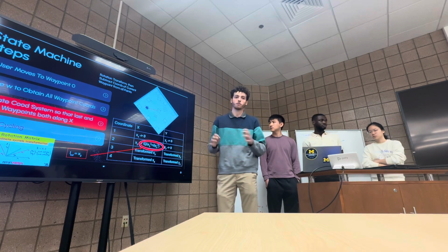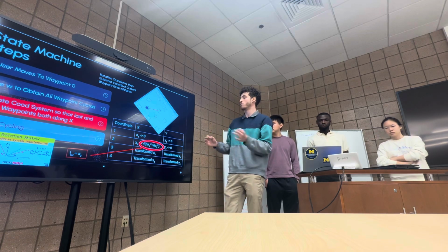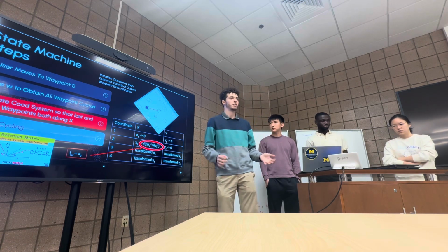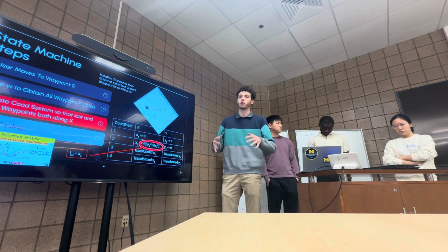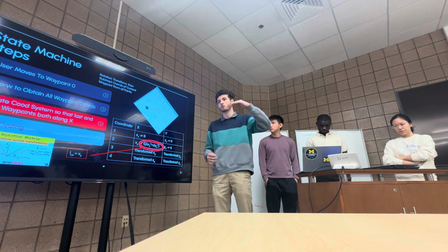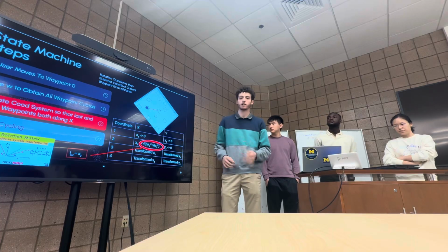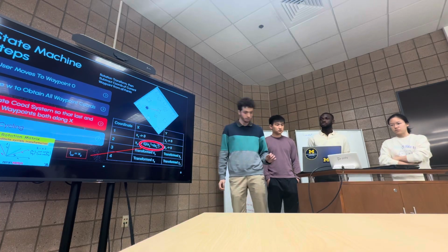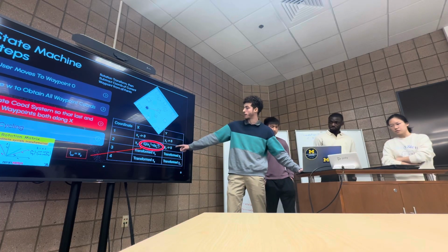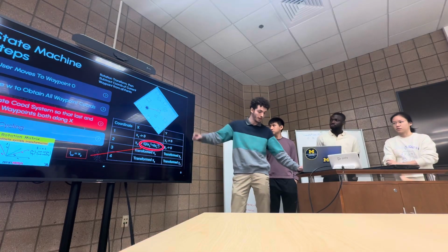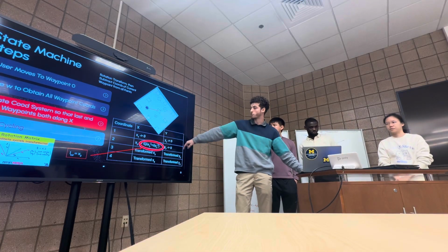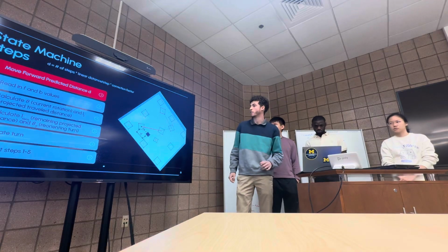We only want to save the rotation, because with rotation matrices, you can multiply them by each other to save the full transform, which will allow us, whenever a new waypoint is added, to just feed it through that set of transforms to get its new coordinate in the rotated system. This will also create the effect that our y coordinate is now just our offset along the F and B directions, and our x direction is just the total distance to our next waypoint.